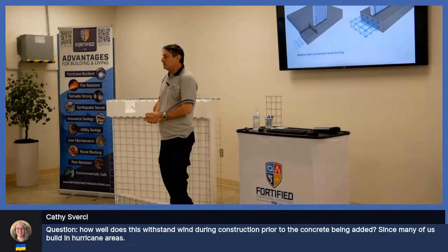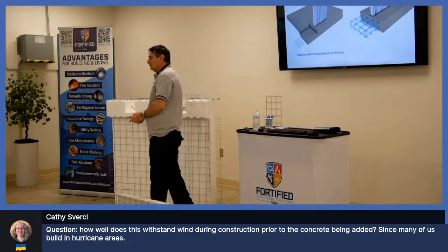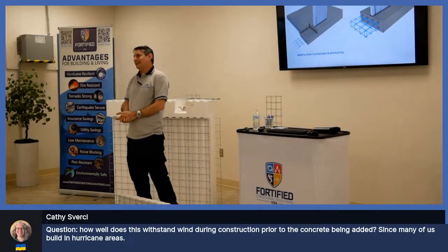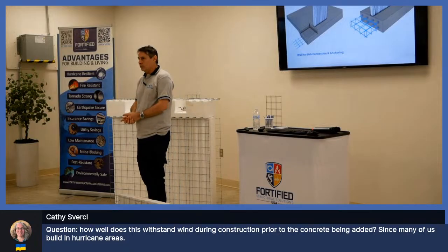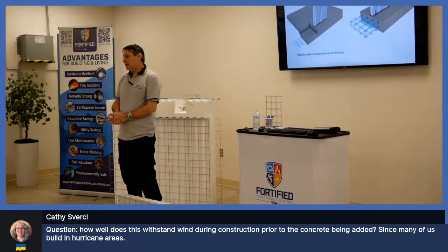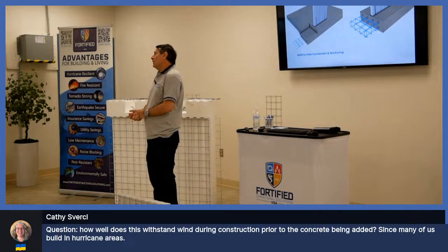Well, the thing is that we have a lot of experience about that, because southern Argentina and the East Coast are wild with the wind. During the process we don't have hurricanes, but we have that. And of course, it's the shoring. You have to add more shoring, bracing, and that's all.